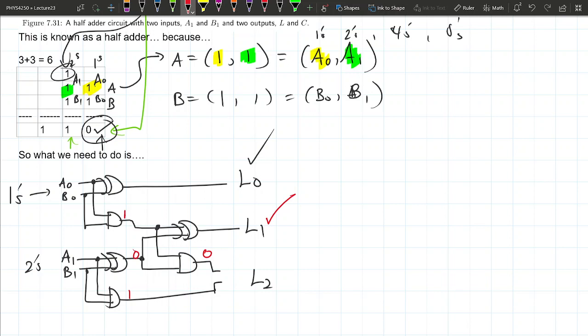In fact, you want a 1 on the other side no matter if it's 0, 1, 1, 0, or 1, 1. What type of gate would that be? Just a regular OR, not an exclusive OR. And that's what gives you the 3-bit output that you want.